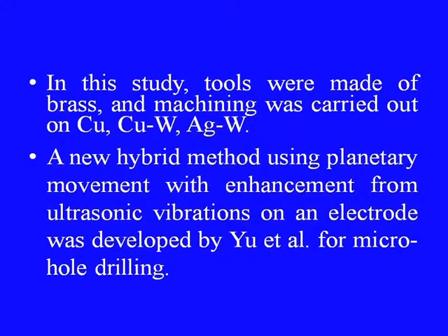In this study, tools were made of brass and machining was carried out on copper, copper tungsten and silver tungsten material. A new hybrid method using planetary movement with enhancement from ultrasonic vibrations on an electrode was developed by Yu and his co-researchers for micro hole drilling. It was found that the use of these hybrid methods can give unevenly distributed gap for bubbles and gases to escape.